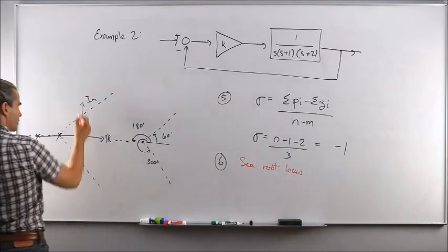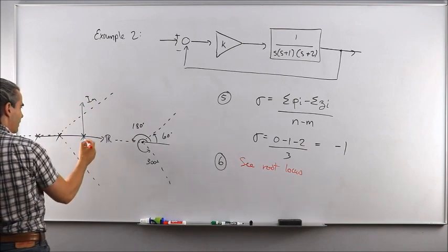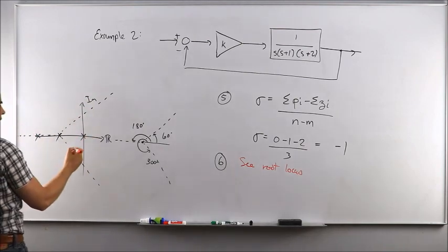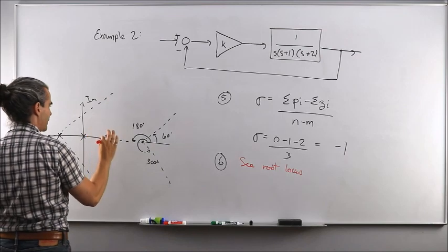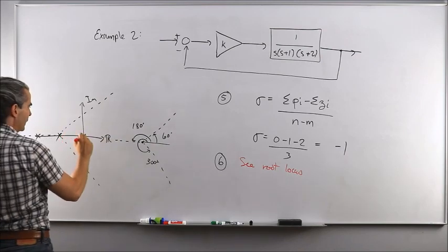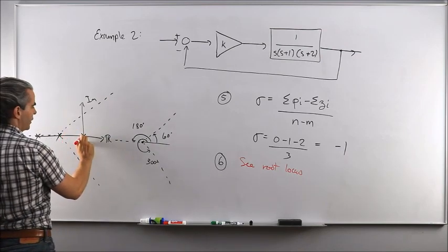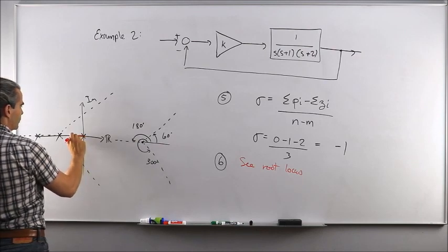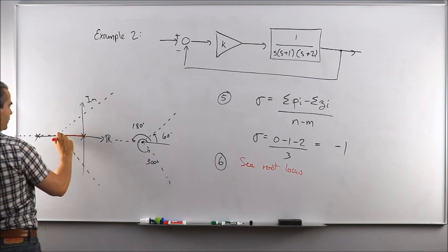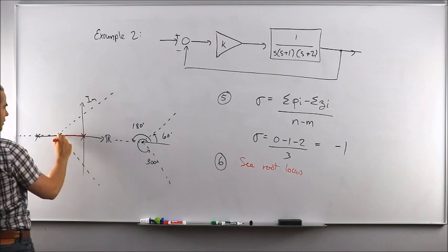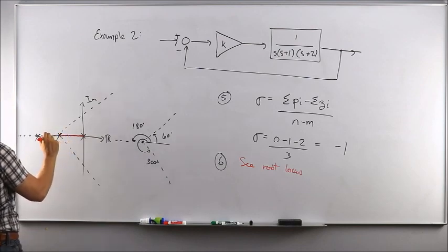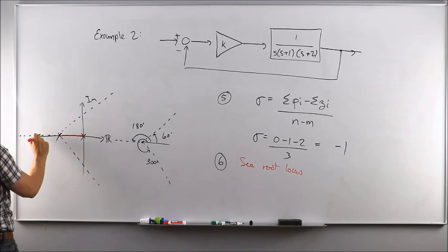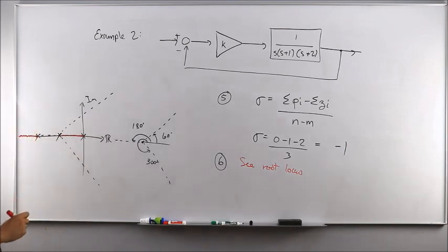Okay? So starting at the imaginary axis, counting towards the left, whenever it is going to be odd, pen down, even, pen up. I'm starting, there's already 1. This is an odd number, so pen down. Oh, this is the second object I encounter, pen up. Oh, third one, pen down, all the way to minus infinity.